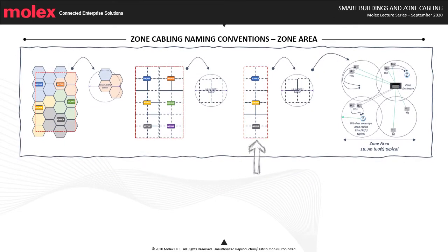A zone area should range from 72 square meters to 720 square meters, that is 775 square feet to 7,750 square feet, to support a device coverage area radius from 3 to 30 meters, that is 32 to 323 feet. Each coverage area may have multiple SOs, TOs, and direct connections from SCPs to building devices. Solid conductor cables shall be used as well in areas which do not have environmental control, such as raised floors, ceilings, warehouses, etc.